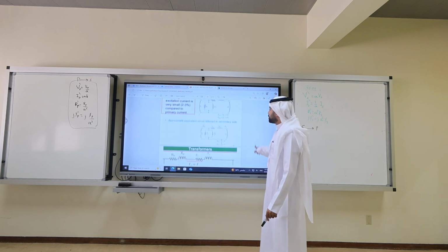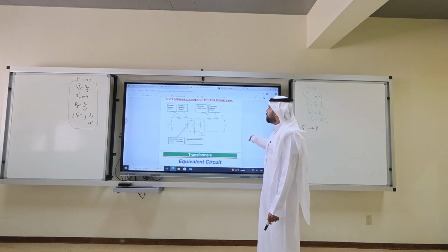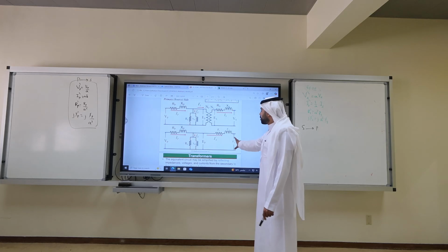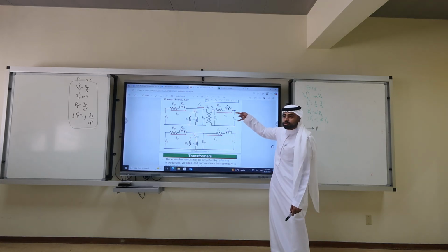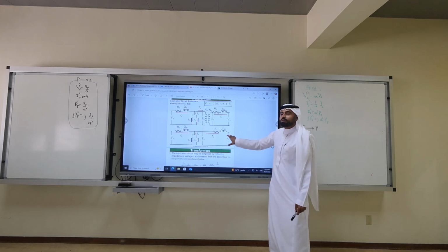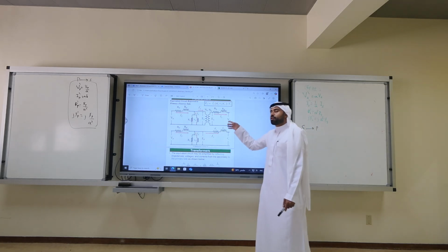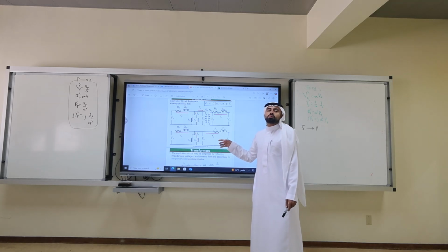Do you connect the load on the model here? You connect the load here. So we call this a load current. It's not VS prime. VS prime is the load voltage reflected to primary, which is reflected to source.